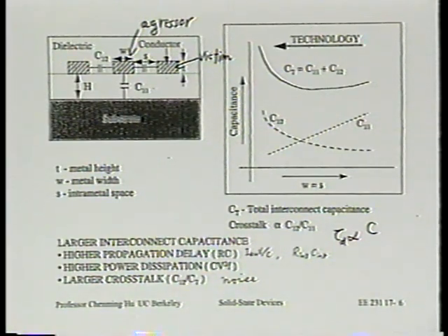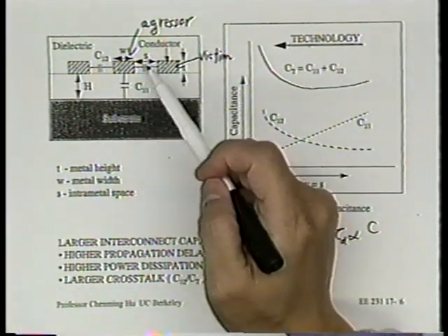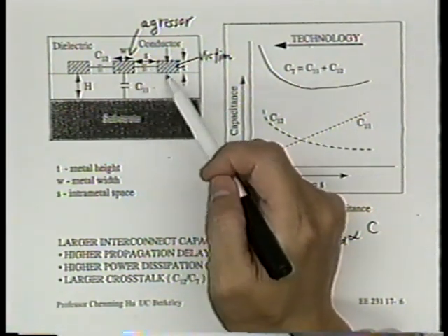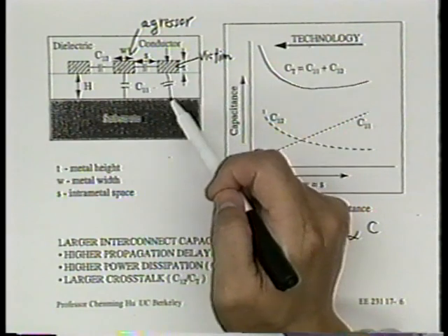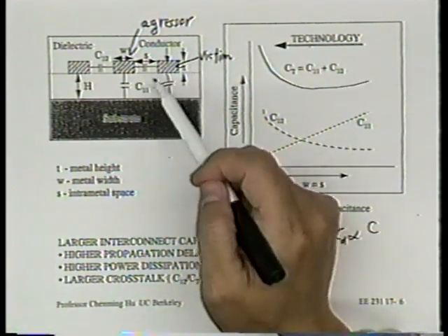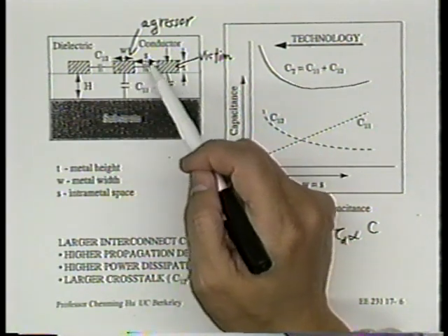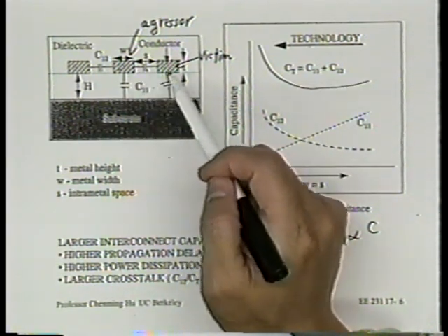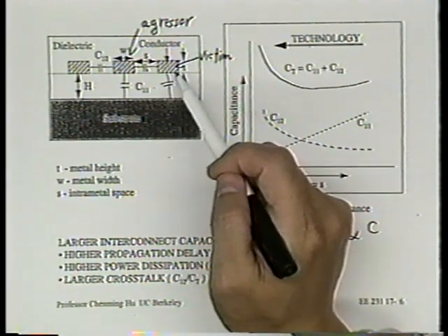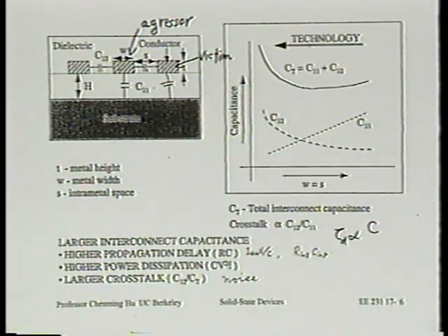The interesting thing is that as far as the noise is concerned, it's not so obvious that capacitance is always a bad thing. Certainly, this capacitance is bad, right? We don't want capacitance with neighbors. But actually, this capacitance in some ways, or other capacitance to ground, is good. Because if this capacitance is larger than that capacitance, then we're not going to see as large a delta V in the noise being produced by the aggressor. Can you see that? Right?